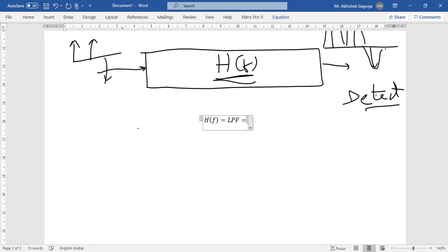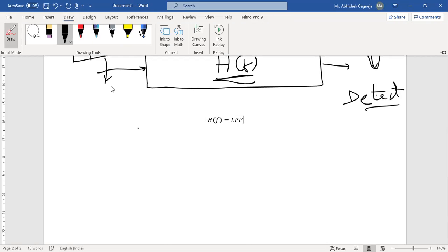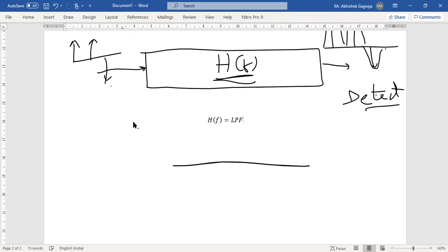The question was, if it is a low pass filter, what should be its bandwidth? Well, since we require that the system should have minimum bandwidth, let's consider the minimum bandwidth. So the idea is that he suggested that h of f be made into a low pass filter, and the bandwidth should be the minimum possible bandwidth. The theoretical minimum bandwidth of any given system is RB by 2, right? And this may have some sort of a positive amplitude A, right?